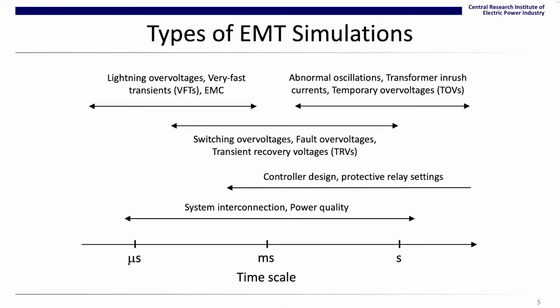Note that if a controller is for power electronics converters used for HVDC transmission, FACTS controllers, and renewable energy interconnections, then the controller must be simulated with its power electronics converters. If this is the case, although I said controller design ranged from sub-milliseconds, the studies should range from sub-microseconds since power electronics converters must be modeled in the simulation.